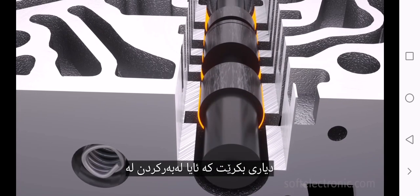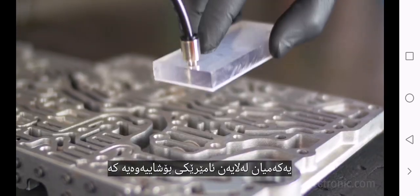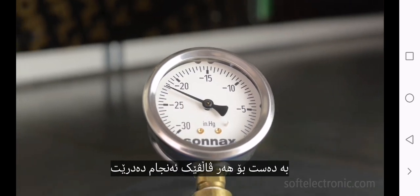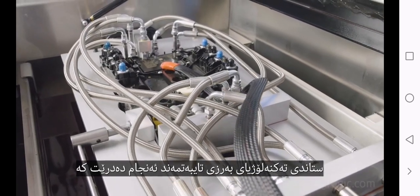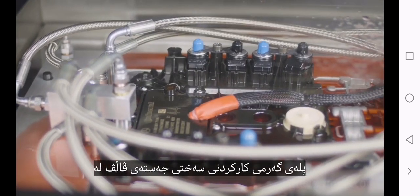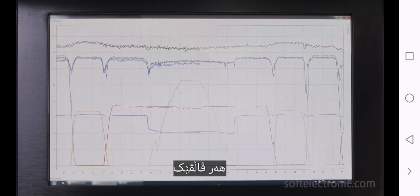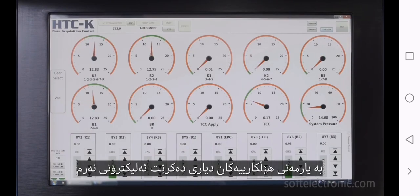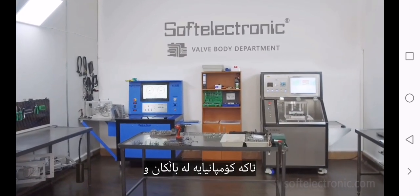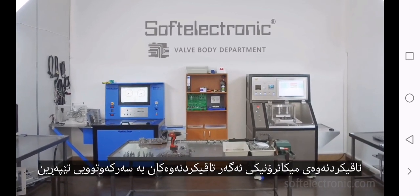To determine whether there's wear in the valve seats, 2 tests are performed. The first one is by a vacuum machine, performed manually for each valve. The second test is carried out on specialized high-tech stands, which simulate the pressure and hard working temperature of the valve body in real conditions. The correct or incorrect operation of each valve is determined with the help of charts. Soft Electronic is the only company in the Balkans and one of the few in the world which owns 2 of the best stands for mechatronic testing.